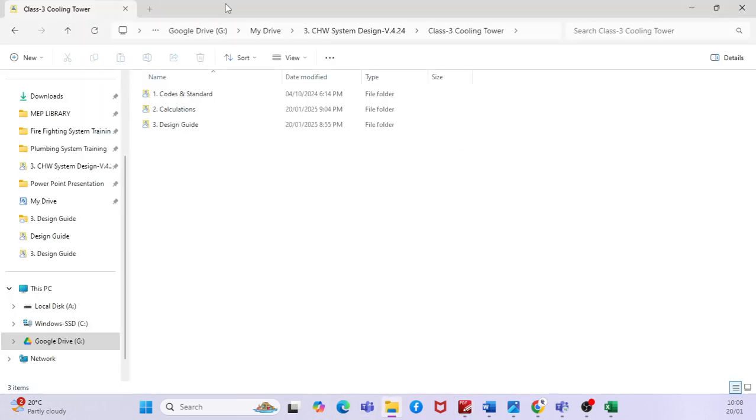See, there is an equation for water and there is an equation for air. I know the equation for air is like 1.2 times something, but this is for water. So for water, it would be 4.186 into your flow rate. The Cp is basically 1000 into 4.186 something. That's the formula basically. We use 4.186 into your flow rate into your delta T, which is your range here, and then you would get your load in kilowatts, if I'm not wrong.